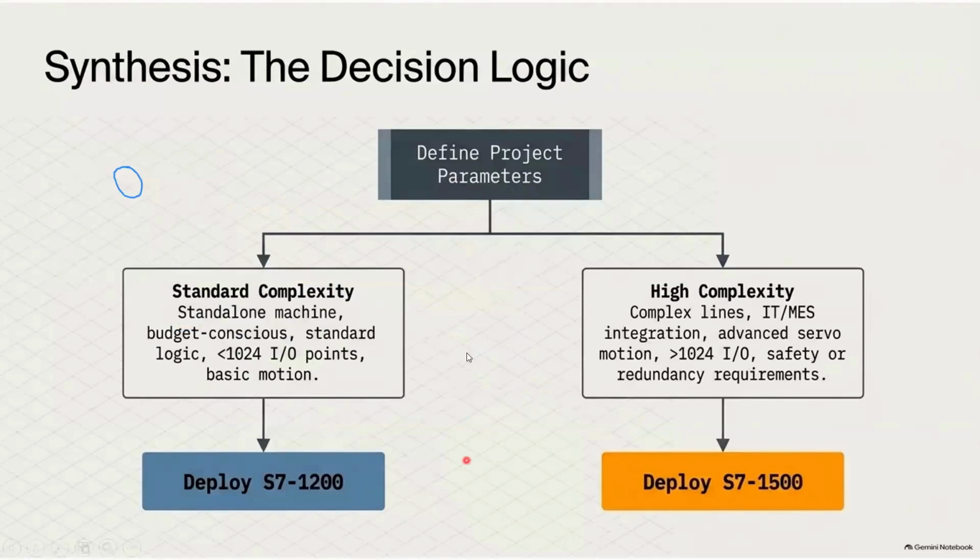If you go through these points, you can understand easily. The S7-1200 is for 1024 or fewer IO points. Basically, S7-1200 is for standalone equipment. And if you have, say, 5 standalone equipment, you can still use S7-1200 in all the locations, and with an extra IO interface module, you can connect all of these to a single HMI. That option is available. But instead of that, you can use S7-1500.